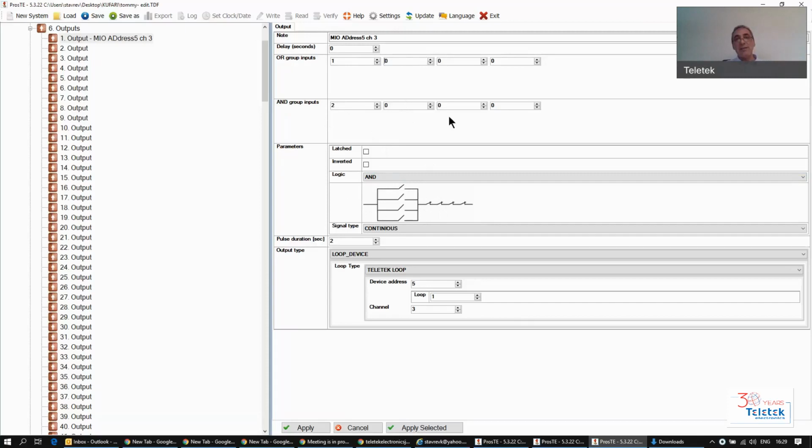This corresponds to the second one, etc. So by putting number 1 input over here on this line that represents this part, as soon as I put a number there, this switch will open up. So now, how is the panel going to react? If the sounders turn on, respectively my input number 1 active, this will close this switch. But the signal will get jumped over here because the second part, switch number 2, input number 2 is not active. Unless there is a fire in zone number 1, and then this input is going to close and the signal will go to the other side to my output module.